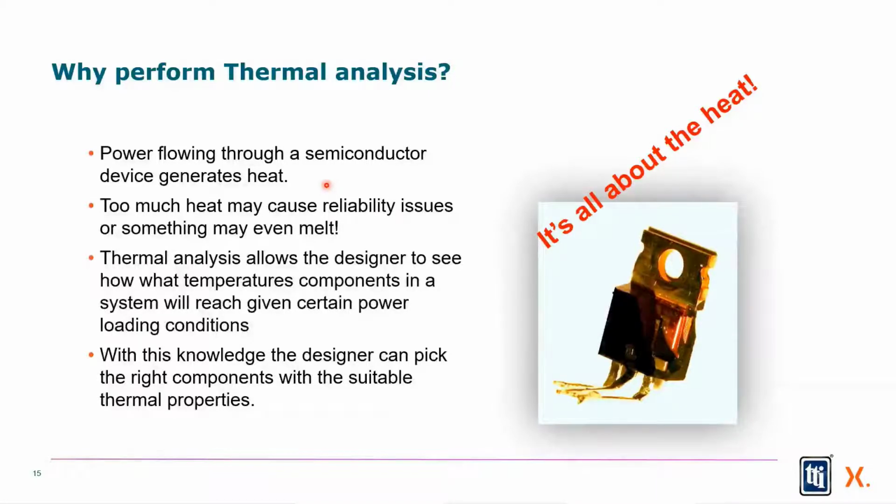It can only do so many million switches or billion switches, depending on what that temperature is, and you will shorten its life if you're running it outside its operating range. So thermal analysis allows you to understand what your application is going to do to the MOSFET. Again, think back to the power tool application.